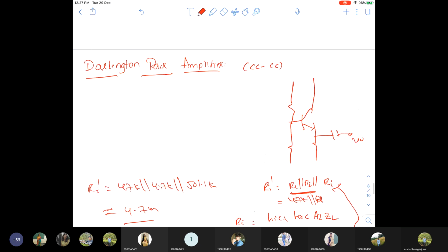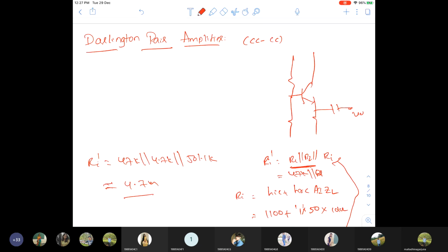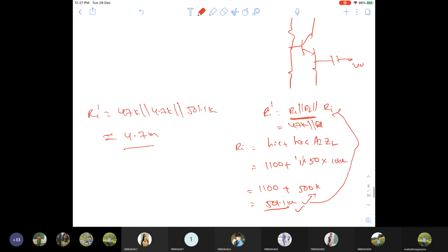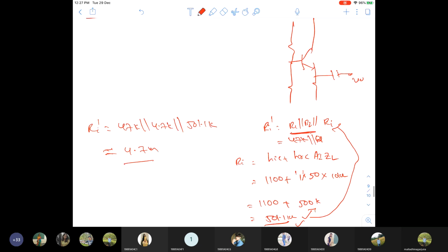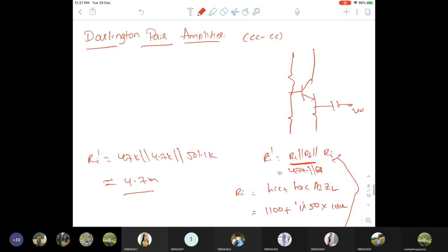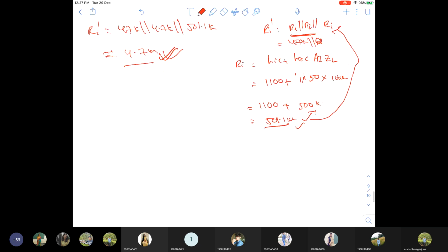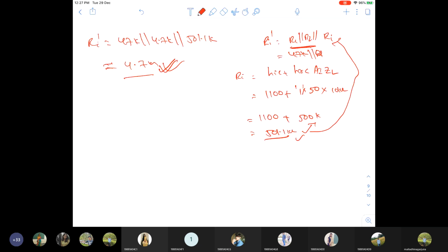So how are the R1, R2 resistors involved in reducing the input impedance of the common collector configuration? You have to take some equations like this, take some random values, and explain. Sometimes they ask. So this is the problem with the common collector amplifier. To improve the input impedance from 4.7K again towards 500K, we move to these techniques.